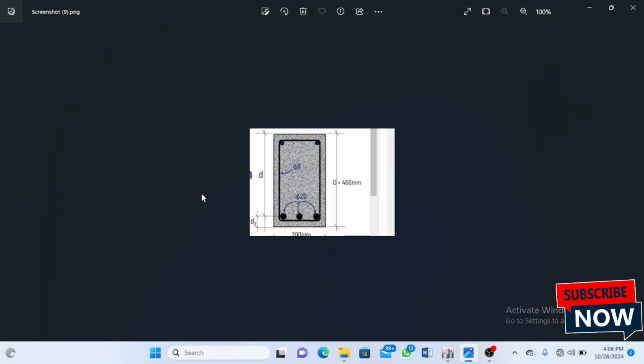So we are going to take this as our beam that we are defining, and the value that the ETABS app is expecting us to input is this one, the D2. The D2 is the cover, the distance from the surface to the stirrup, and the size or diameter of this stirrup.